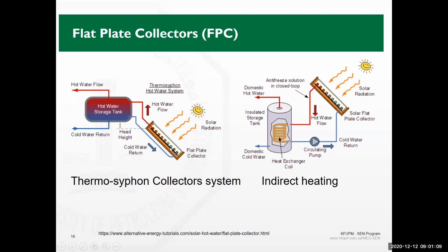So it could be like that, especially if you are going to put ethylene glycol with the water. You don't want the ethylene glycol to go to the hot water supply to the space, but rather you put a heat exchanger like what you see, the one in the right here. You have the heat transfer fluid going into coils, whereas the domestic hot water is going through the shell side of that heat exchanger. So it'd be something like that.